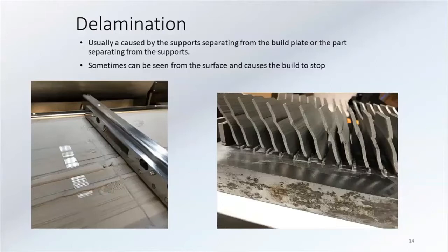On the top surface, it looked overall like I was doing well, other than on the edges, where I was not spreading powder over the next layer each time. On the edges, I was seeing bare metal, and that's because the part had propped up. It was probably around 100 microns above my layer, and my layer was 60 microns. And so, again, new powder wasn't really spread. Most of these failures, once you have your machine honed in, or if you're doing what's recommended to you, should not be an issue.